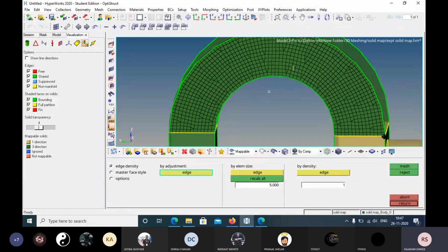Now I will click on select entity. You can see here the elements on this face are selected. Select the mask and reverse. Okay, these are the two-dimensional elements. You can see here. These two-dimensional elements are not required for our analysis because our geometry is 3D geometry only, and there is no 2D part. So these elements we have to delete. Now how we can delete it? I will go to the return, delete elements display, and say delete. Return from here and click on unmask all. You will get only 3D element.